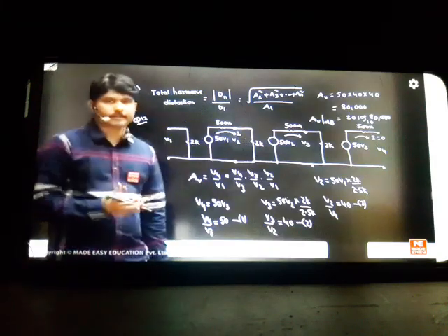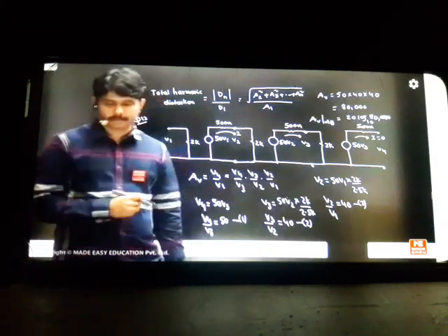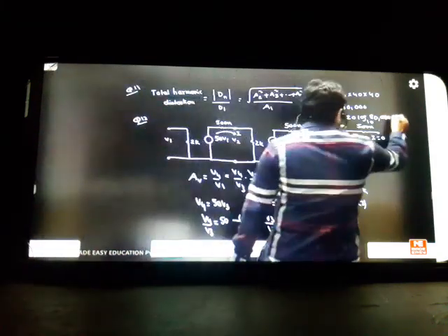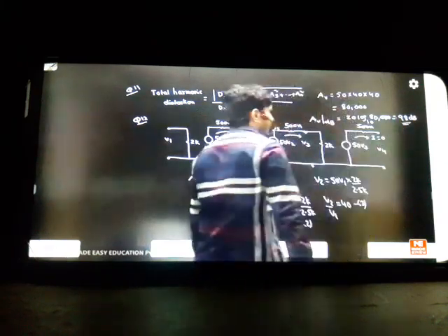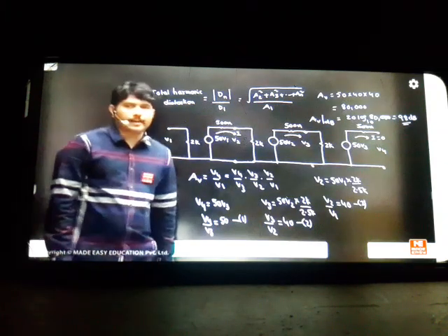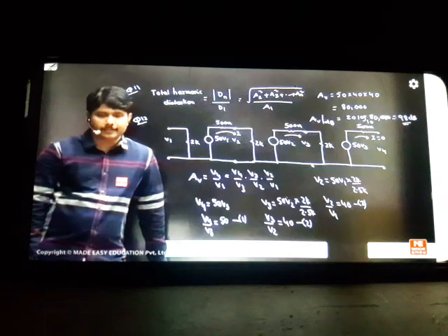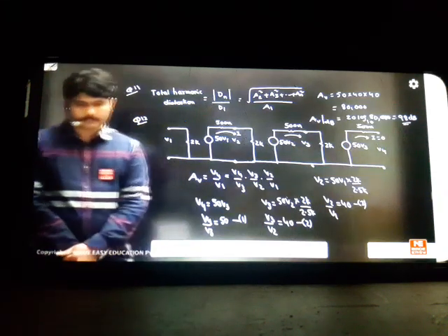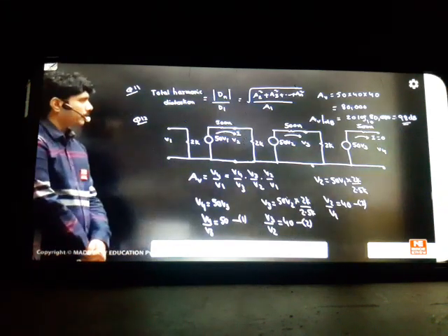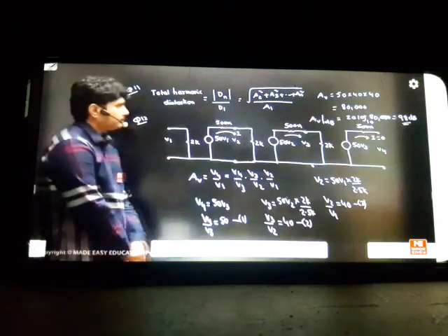In the coming class, all the op-amp questions and gain problems we do in decibel scale. Just a 20 log you applied. If you apply 20 log for that, this answer will come as 98 decibels. So in decibel scale the magnitude will become a very small value. So 80,000 in magnitude we can also call as 98 decibels in decibel scale. So this completes your concept of how to do it. So question number 12 is completed nicely.